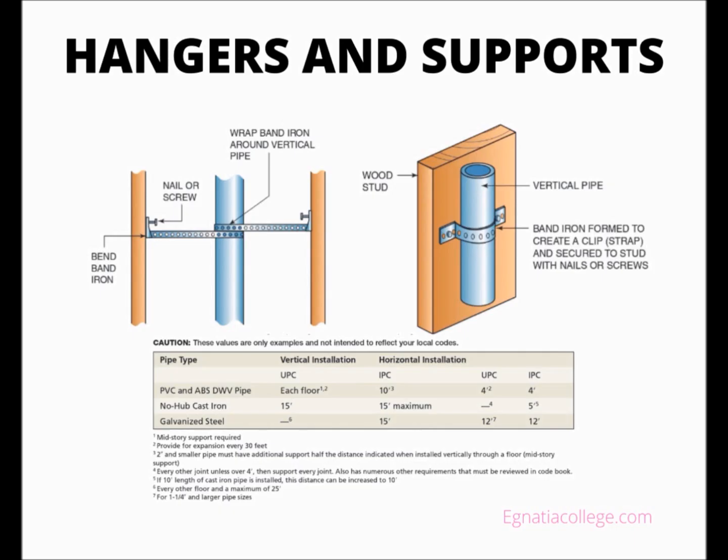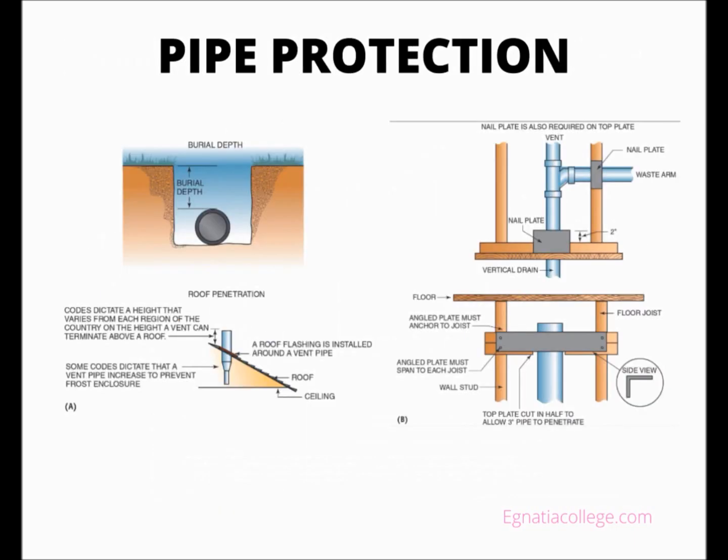Pipe protection. Like water distribution piping, DWV piping must be protected against nails and screws used to install wallboard and wood trim during the final phases of construction. A metal stud guard, or nail plate, that protects the piping is available in several sizes. Most have a nail-in feature to drive into the wood boards with a hammer.